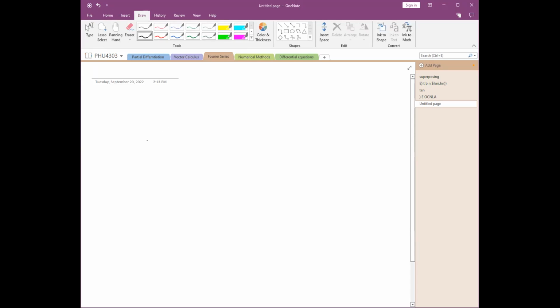How does it work? Well, its behavior is quite simple. You have an electromagnet, which you call L1, and there's a thin metal strip like this. And there are two more metal strips connected like this. These ones, the ones I draw in blue, are stationary, they are fixed, they can't move. However, this other one, the one I draw in, let's say, red, is flexible, it can move.